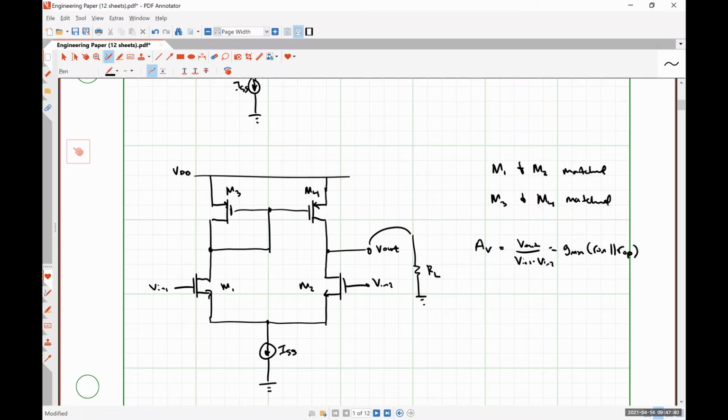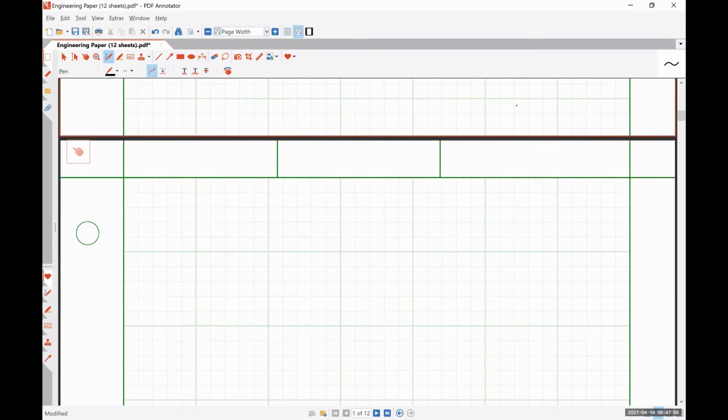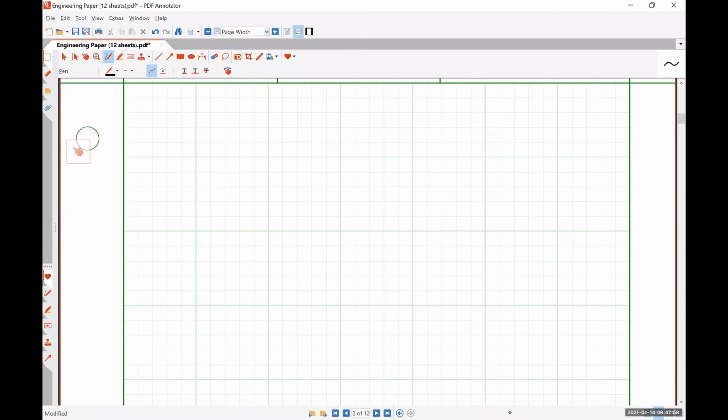Yeah, the only difference there is that you're not going to have base currents to worry about. So you don't have to worry about that error that goes into it, because the error is because base currents are drawing some current away from your reference. So if we have a BJT current mirror, let me just draw one real quick.